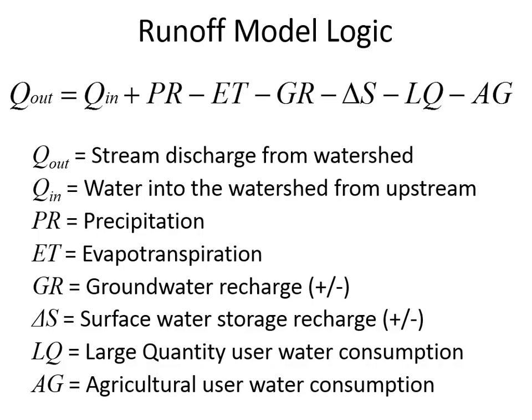And so groundwater recharge over the long term, you can assume, is steady. Here in West Virginia, that's a fair assumption. There are places like El Paso, Texas, where that's a horrible assumption. Or in the United Arab Emirates, where they're completely exhausting all of their groundwater resources. In the western United States, in Idaho, a lot of agricultural regions have had a net negative groundwater recharge for a number of years. So they're consuming groundwater. But in the case of this watershed, it was fair to assume that over the very long term, groundwater recharge is steady.